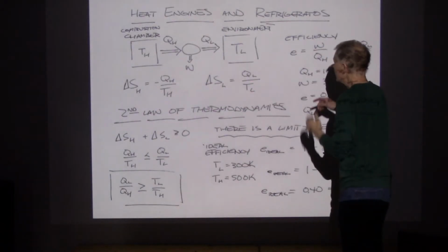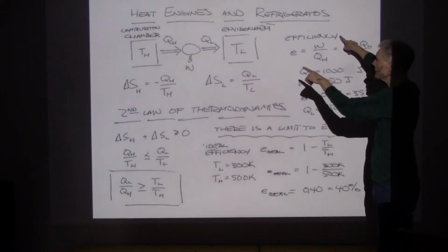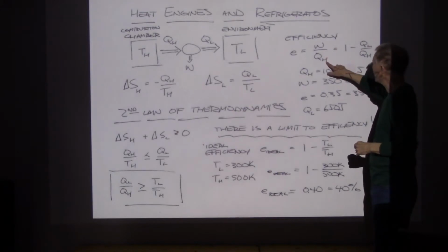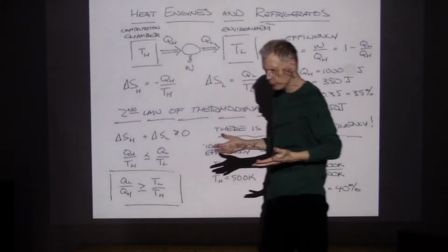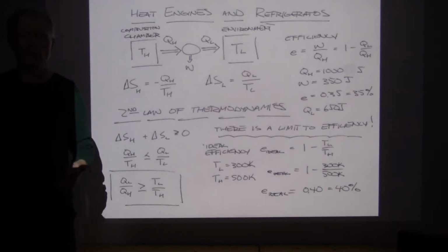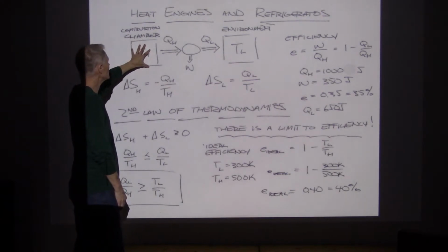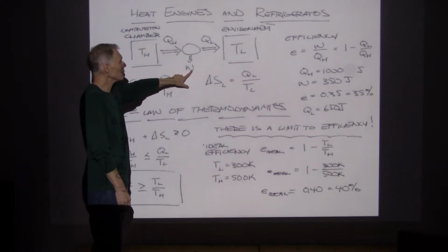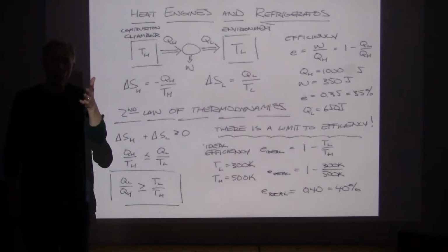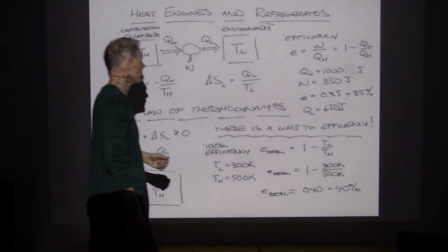First of all, I want to come in and define an efficiency. How efficient is my heat engine? I'm going to define efficiency as the work divided by the thermal energy that we've generated in the high temperature region. So again, if I generate 1,000 joules of energy here, how many of those can actually be converted into mechanical energy, something that will operate my car, generate some electricity, something like that.